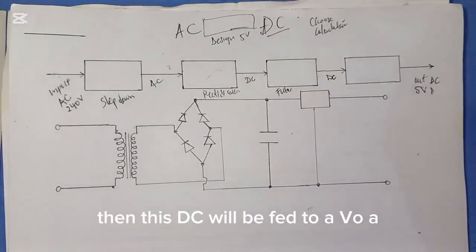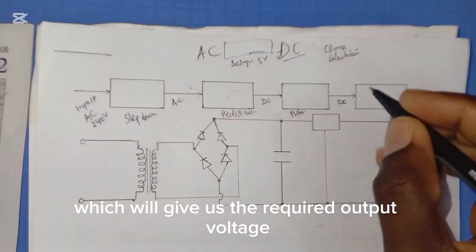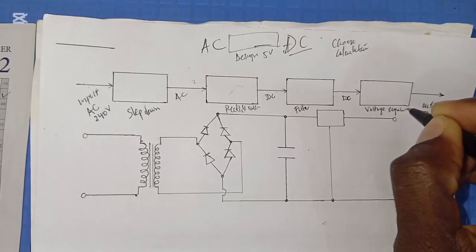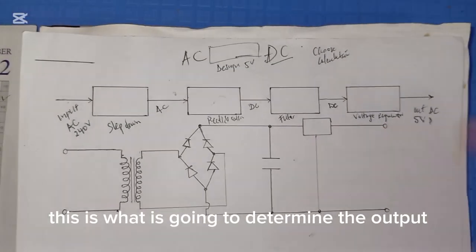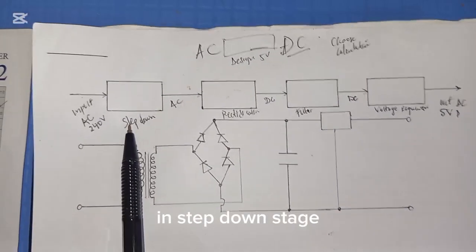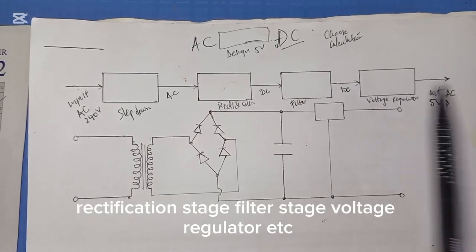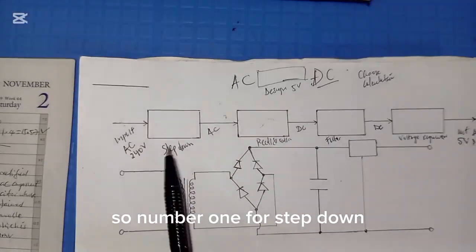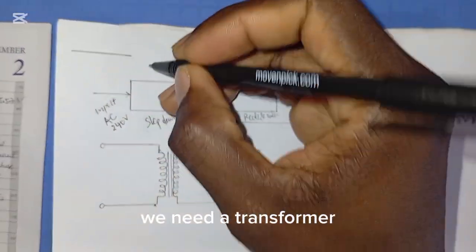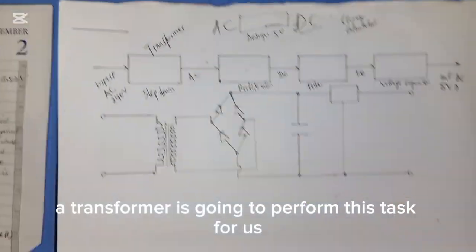Then this DC will be fed to another part which will give us the required output voltage, which is called a voltage regulator. The voltage regulator is what is going to determine the output. Now, what are the components we are going to use in the step down stage, rectification stage, filter stage, voltage regulator, etc.? Number one, for step down, for us to be able to step down the main AC to a manageable voltage, we need a transformer. A transformer is going to perform this task for us.